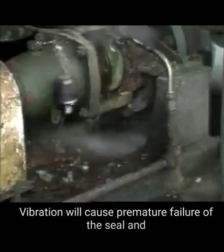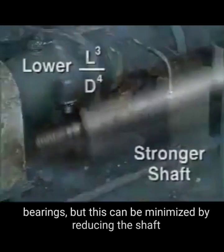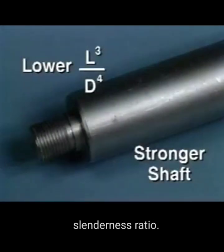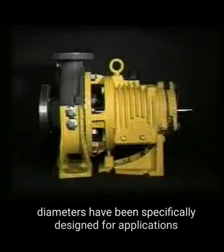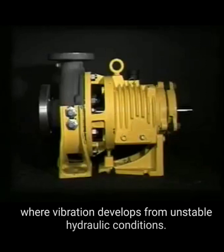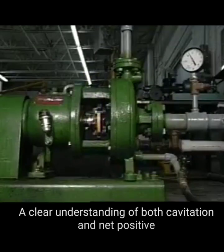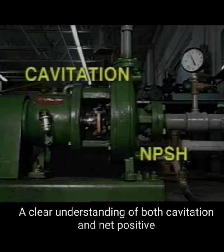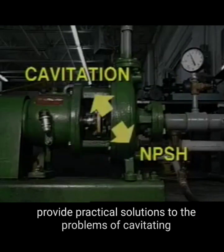Vibration will cause premature failure of the seal and bearings, but this can be minimized by reducing the shaft slenderness ratio. In addition, short overhang pumps with large shaft diameters have been specifically designed for applications where vibration develops from unstable hydraulic conditions. A clear understanding of both cavitation and net positive suction head and their relationship to each other will provide practical solutions to the problems of cavitating pumps.